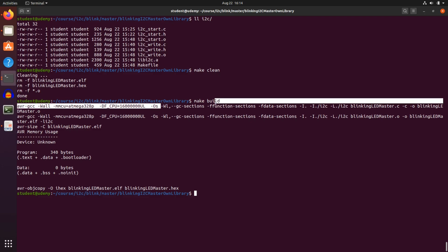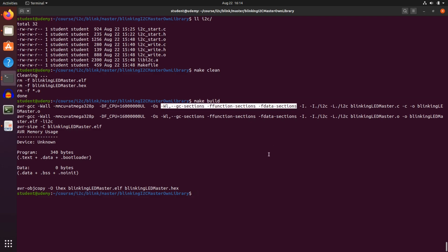Remember the function of these parameters? These parameters make sure that the linker is able to remove data and functions which are not used, since they are all in separate sections. That is for the compiler. And the linker can garbage collect these kinds of sections which are not used. What happens if someone is not using this parameter?